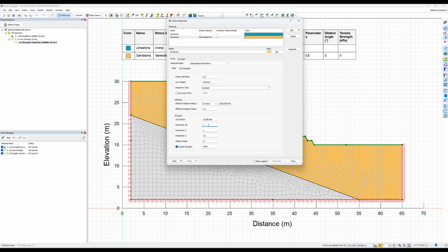I will then specify the Hoek-Brown parameters m_b equal to 0.0456600489, s equal to 2.2603294 × 10⁻⁶, and a equal to 0.53823676. These very specific values were copied over from the parameters determined by the limit equilibrium Hoek-Brown material definition using the intact rock parameter, geological strength index, and disturbance factor.